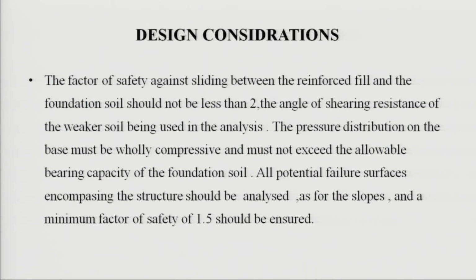The pressure distribution on the base must be wholly compressive and must not exceed the allowable bearing capacity of foundation soil. All potential failure surfaces comprising the structure should be analyzed. As for the slope, a minimum factor of safety of 1.5 should be ensured.